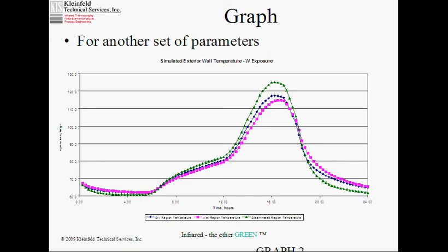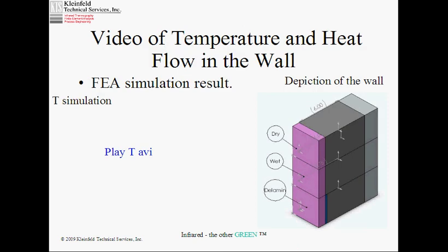This is a west wall, same building, same time of year, same atmospheric conditions, same solar characteristics, and you can see it's the same but different. It's the same in that the nighttime wet is the warmest, daytime wet is the coolest, but the shape of the curve has changed because the sun gets to the wall at a different time of day, but the wall is still seeing the air temperature changes at the same times as the southeast exposure did. So you get a different shape, it's offset.